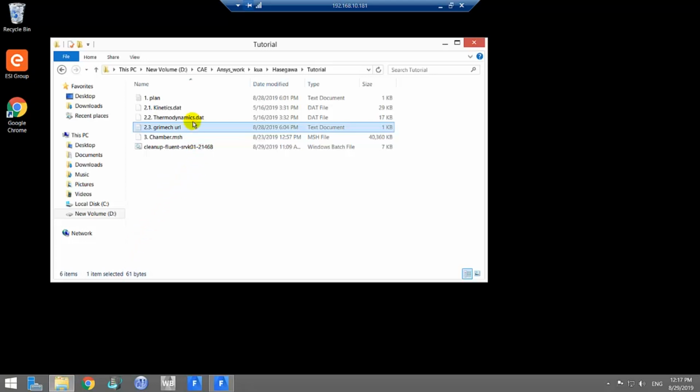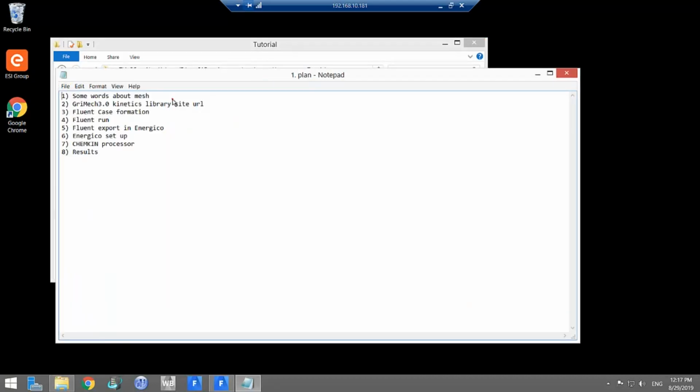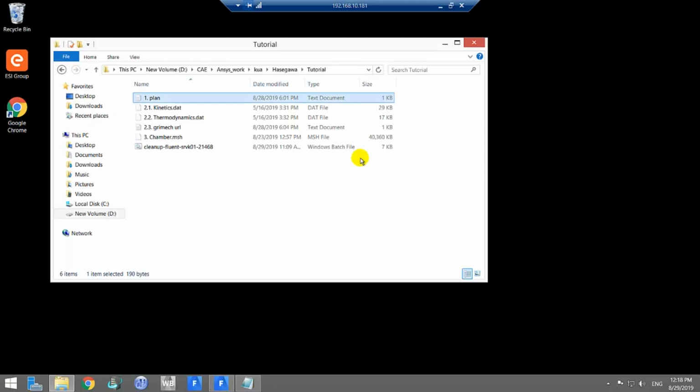Well, here's our working folder. In this series of videos we won't consider geometry and mesh generation. We'll take a prearranged mesh file that you'll be able to download from the link below. Next, we'll consider how the non-premixed combustion model can be set up in Ansys Fluent, what chemical libraries exist and where it is possible to take them from. And finally, we will carry out data transfer from Fluent into Energico and from Energico into CHEMKIN-Pro.